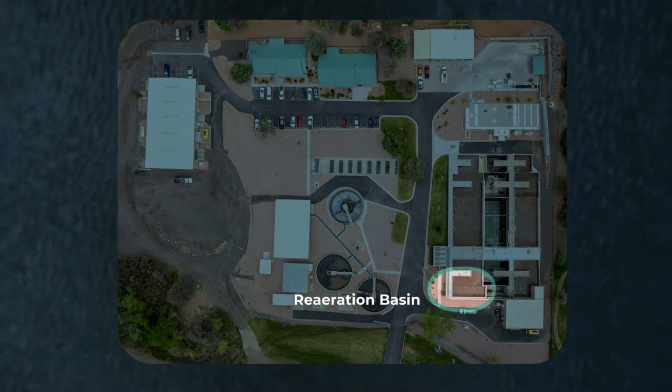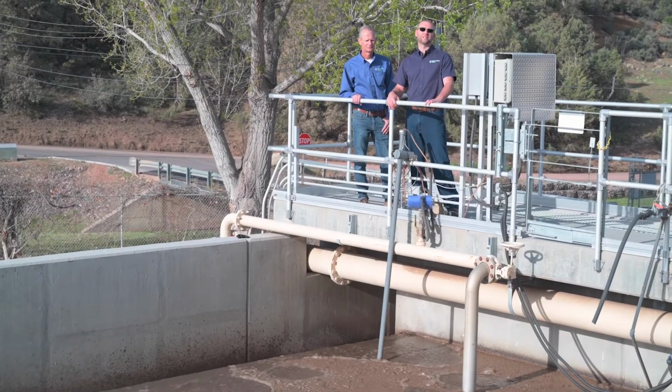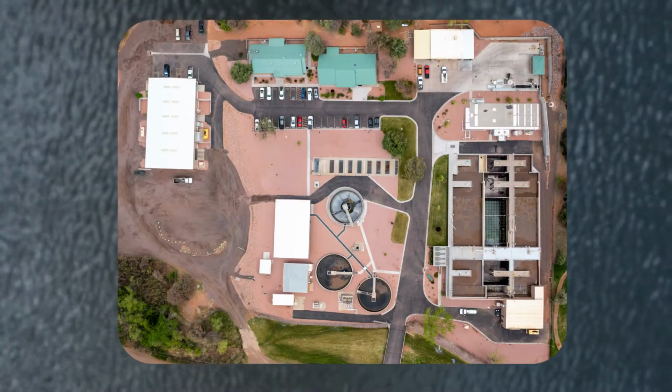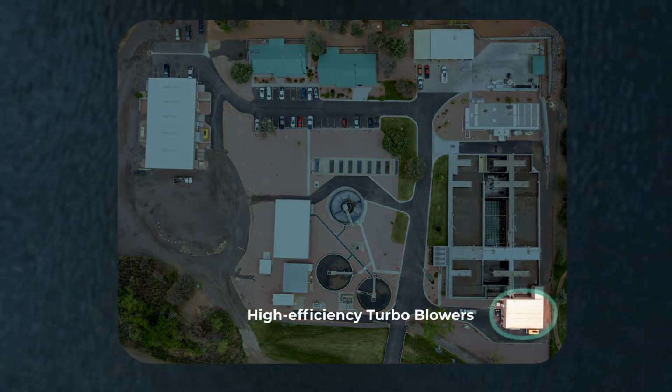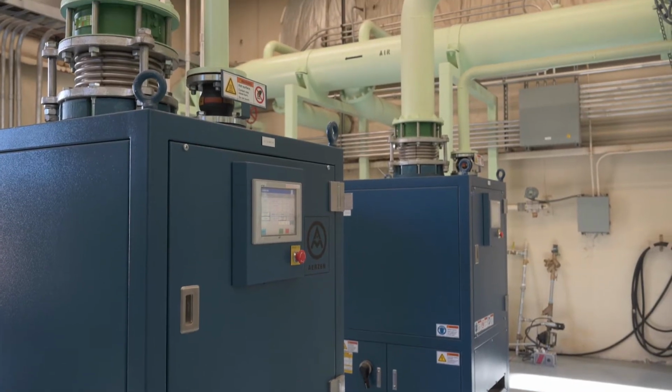This is the re-aeration basin, where we give the bugs a small burst of air before they go to rest in the clarifiers. We're now in the blower building, and this is where we use high efficiency turbo blowers to supply air to the treatment process.